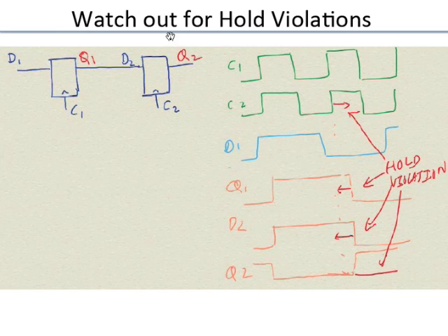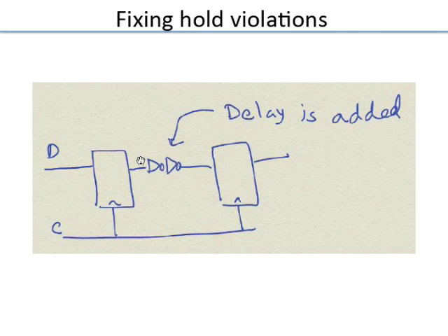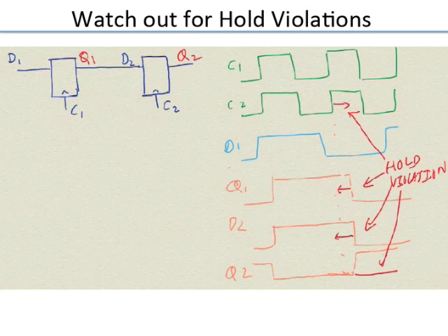Exactly. So what you need to do is, it's happening too fast. So this hold time violation has to be fixed by introducing what are called delays, buffers. In industry parlance, these are hold time fixes where buffers are put. After the design is done, this problem can happen for the fast paths, really the fastest paths, because this cannot be the critical path in your design, since it's just a piece of wire. Critical paths don't have this problem. It's really the fast paths, so you have to slow down the fast paths by introducing delays to fix the hold time problem.